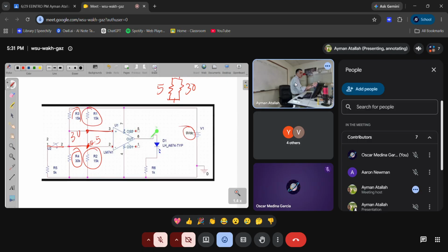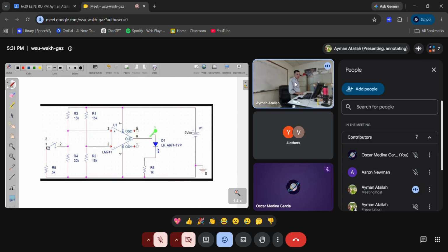Okay. So let us build this with PSpice right now. We have everything. Make sure to put 2 seconds here. We are going to use a transient simulation for 4 seconds. You just write 4, and the maximum step size 1 milli, 1M. And let us see what will happen to the voltage here.